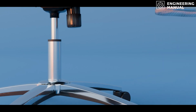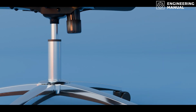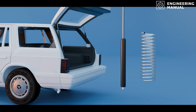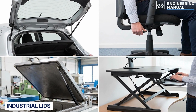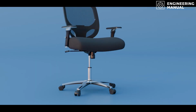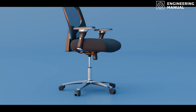Another constraint is velocity-dependent damping. Internal flow through orifices introduces nonlinear resistance, which can be used intentionally for motion control, but complicates pure force modeling. Gas springs are therefore used where smooth, assisted motion is required: hatchbacks, adjustable seats, industrial lids, and ergonomic mechanisms. Their value lies in force modulation and damping in a single integrated component.